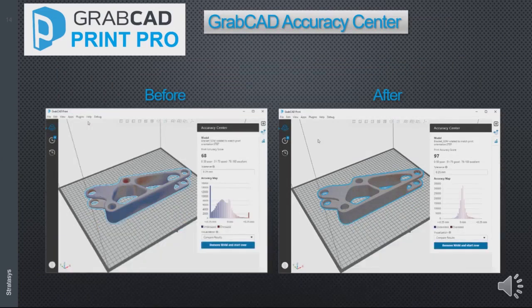All right, let's talk about GrabCAD Print Accuracy Center. So the Accuracy Center is a tool within GrabCAD Print that we can use to correct for warpage in our models. So this actually works in a closed loop fashion. So we print the part, then we take a 3D scan of the part, and then we correct the model geometry to counteract the warpage that we're seeing in our 3D printed parts.